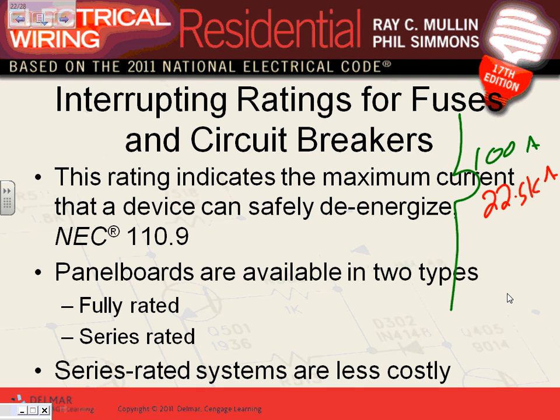We're not going to talk about the electronic circuit breakers yet. We will open this can of worms as we move to the commercial industrial. Thermomagnetic circuit breakers, you're looking at them right in here. That's what they call the thermomagnetic circuit breakers. Why are they thermal? Because they work on heat. Why are they magnetic? Because there's a component that works in a short circuit, in a magnetic force, to open the circuit breaker fast. So, any question, guys, about the circuit breakers?